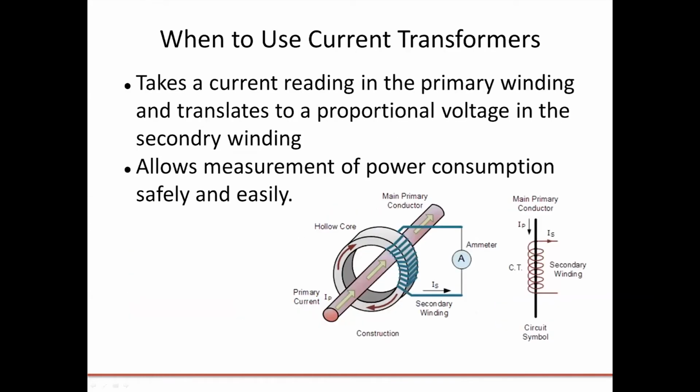Our current transformers transform an input current into a readable output voltage. They always work in conjunction with another sensor module, like one of our DN and DNM series voltage attenuators, or with one of our smart power meter modules. The primary winding replicates current from the power source, and the secondary winding produces a proportional AC voltage. You use a CT in conjunction with another module or sensor to take power readings from machinery in use.